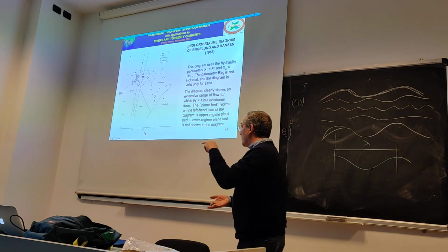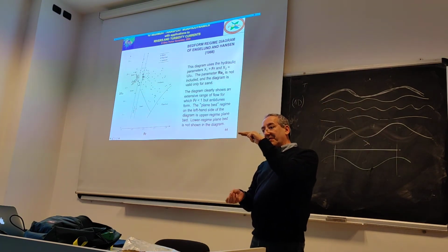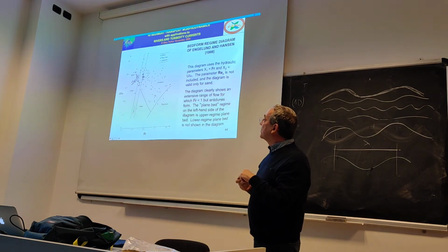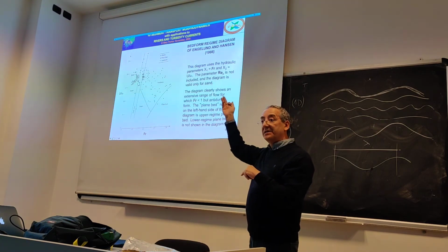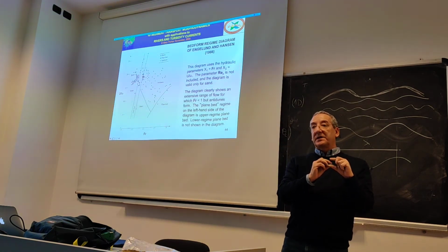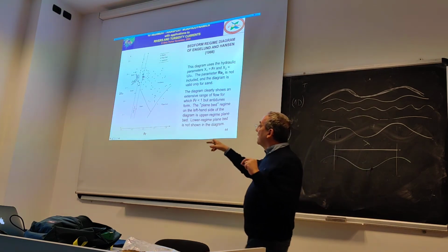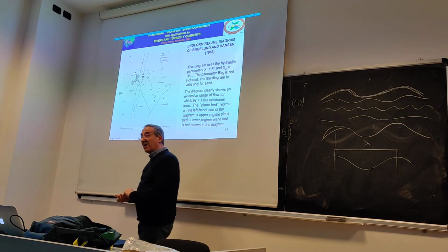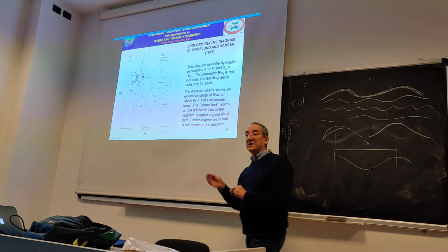A small value of the ratio of the grain size over the flow depth gives you a value of this coefficient of more than 20. If you go to shallower flow or to coarser material, this ratio increases, and then this conductance coefficient, the Chézy coefficient, goes down and goes to 10.